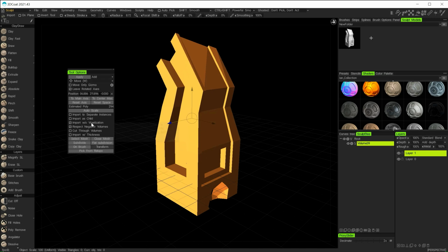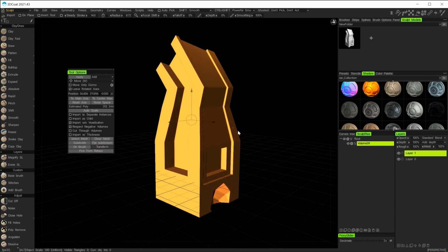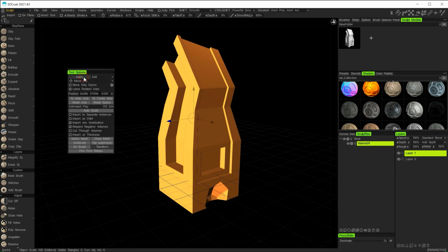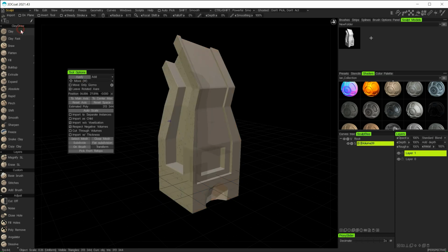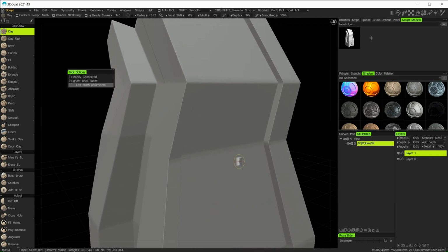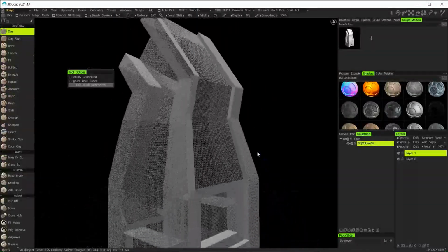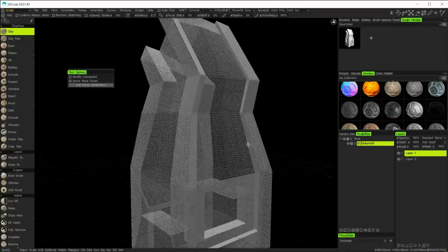And this time, with this one selected, I'll hit flat subdivision, and watch this number here. As I hit the flat subdivision, it starts to go up, so I can start to increase the subdivision, and that should do. And now if I hit apply, and I'll just change the tool, you can see that now it's brought in an object. And if I hit W on my keyboard to see the wireframe, you'll see it's a much denser object because it's been subdivided however many times we did that. So we've got a tri count down here of roughly 313,000.